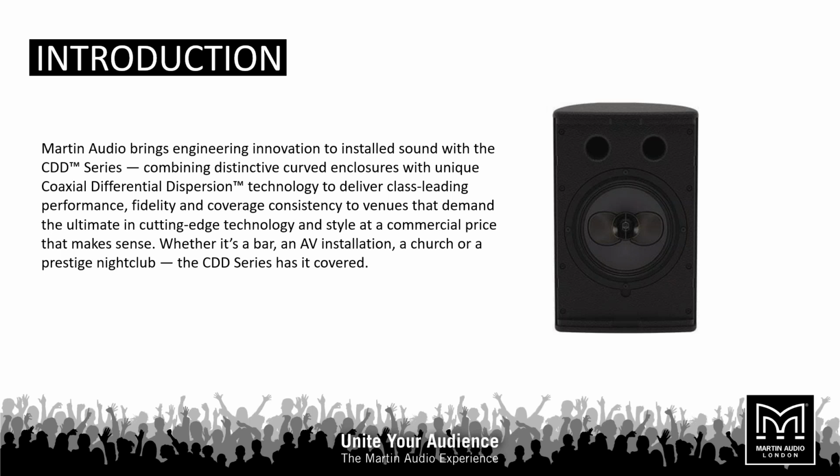And of course, one of the most striking things is this coaxial differential dispersion driver that you can see there, where we have the HF unit mounted on top of the LF unit, giving us our coaxial loudspeaker. And then, of course, you can see the differential dispersion waveguide there, which is actually mounted onto the LF, giving us our horn throat, all orientated from one acoustic center.